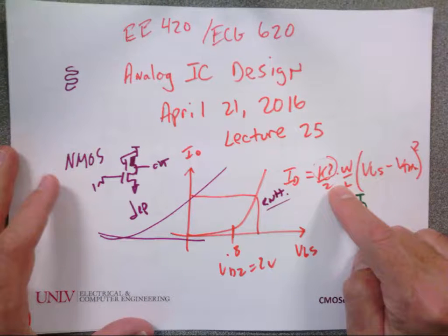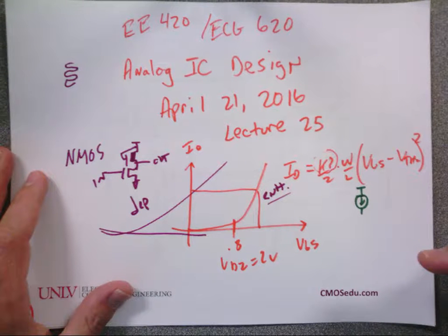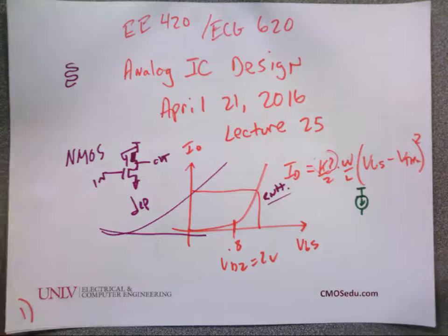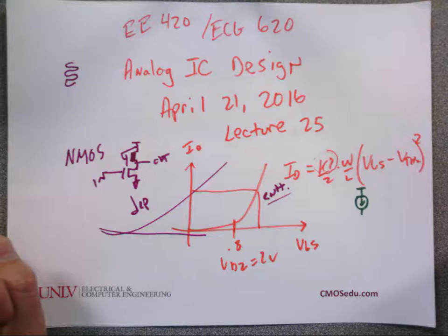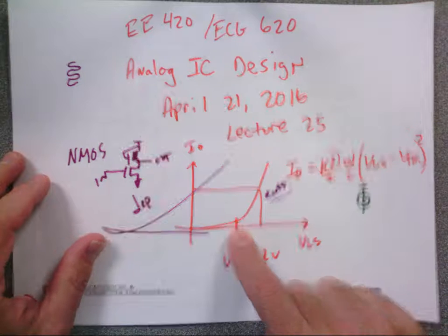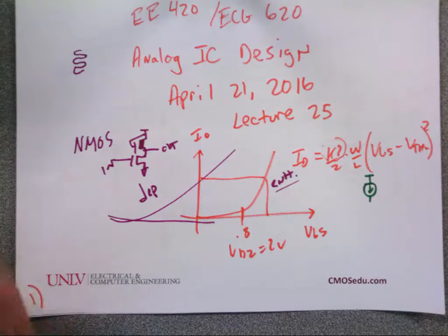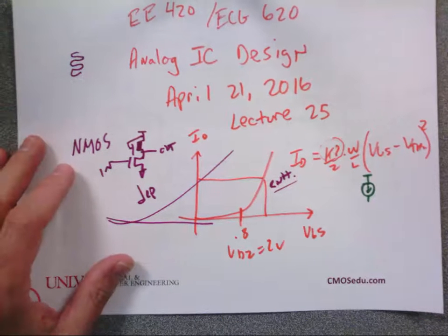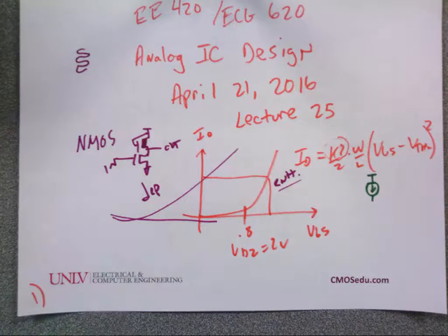You can't get a value for KP because it changes based upon the size of VGS and the VDS. I already got how to get gm and how to get W and L, just like we did at the end of chapter 9. The problem is VTH, because I'm trying to calculate VTH. The PMOS is negative 0.9 something. Remember, you get the VTH by looking at the plots. You get everything by looking at the plots. We're not doing anything different than what's in the book for the short channel process. If you think long channel process, we're saying here are some long channel parameters, and the whole point of those is so we can do hand calculations without just reading values off the charts.